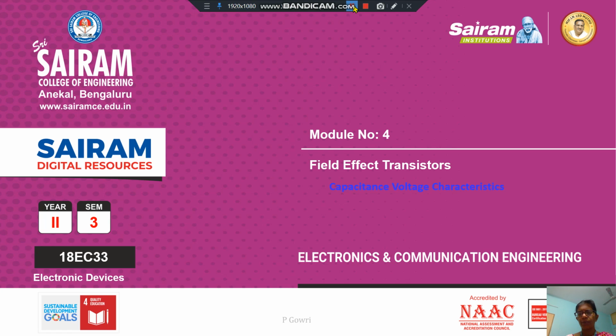Welcome to the video on the capacitance and voltage characteristics of the MOS capacitor. In the previous videos, we have discussed what is meant by a MOS capacitor, and how to understand the working principle of the MOS capacitor using the energy band diagram. We have three regions of operation: accumulation, space charge region formation, and inversion layer formation. Now, in this video, we will be discussing the capacitance-voltage characteristics in these three regions, and also we will be studying the frequency effects.